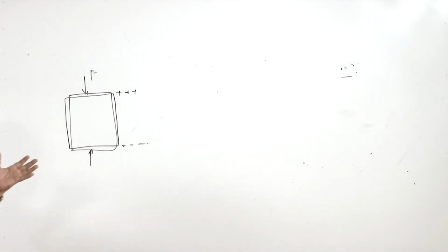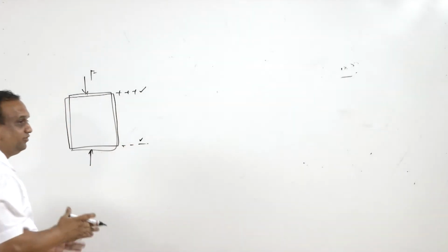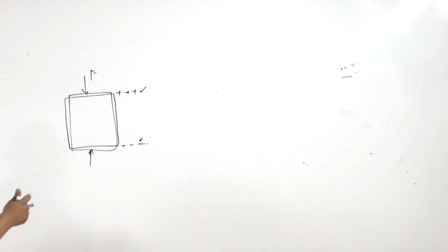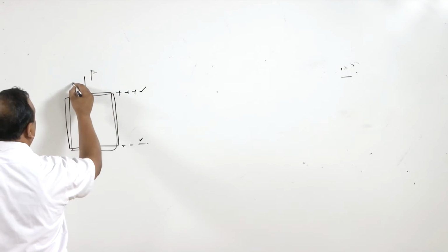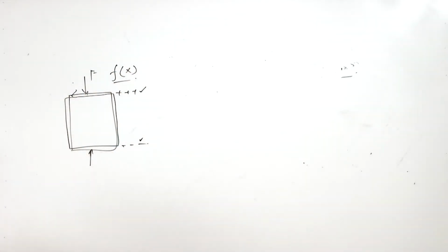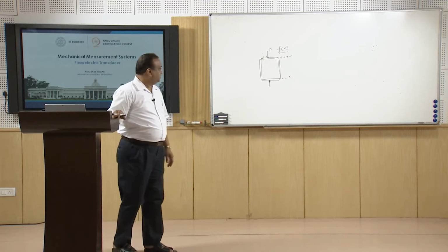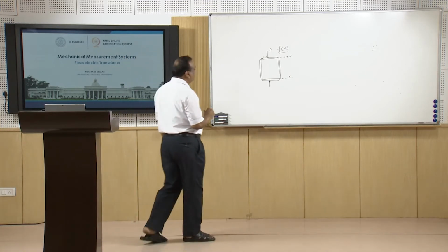So, either we charge opposite faces and deformation takes place, or we deform the substance and charging of opposite face takes place, vice versa. Right? Now, we can have relation between the charge developed here and here, it is sort of capacitance, right, and with the displacement, function of displacement. This is the basic working of the piezoelectric transducer, and this property of transducers is for many uses.